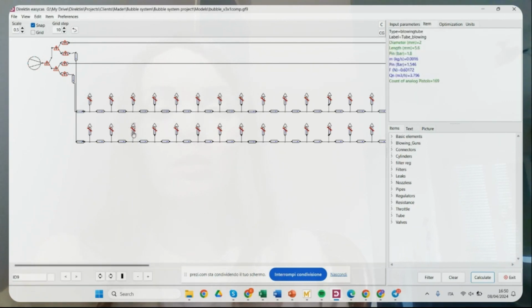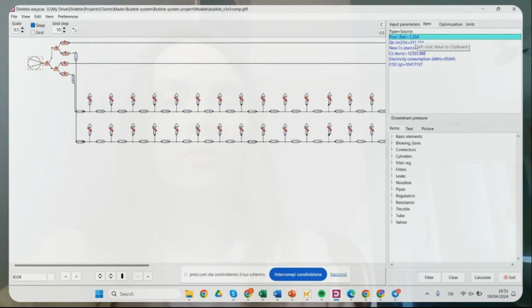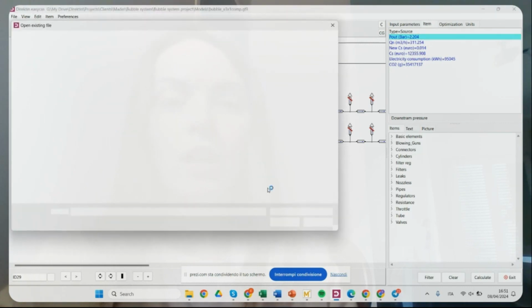for that application. So in this case, for example, we had the higher diameter of the orifice. Before it was 1.5 millimeters, here it is 2 millimeters, and you can see how dramatically it has already changed the consumption of the compressor. We would think, okay, just a half a millimeter bigger hole, but it's twice as much required flow rate, and the pressure level is 2.2. Sorry, here I showed you again the one compressor, but I also have the model for two compressors.